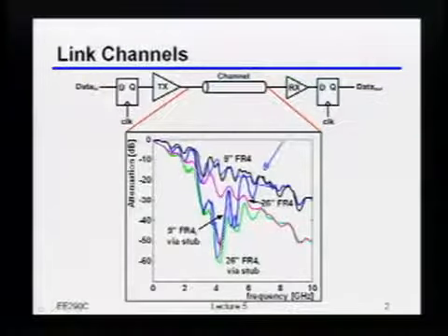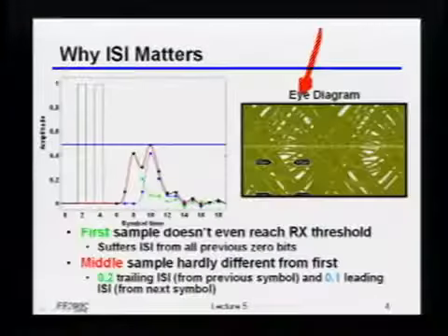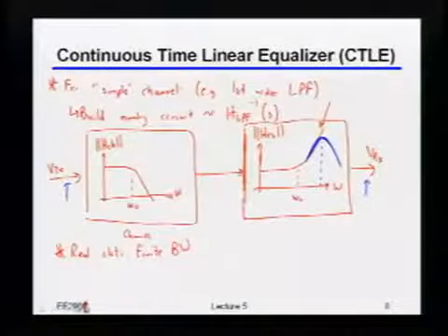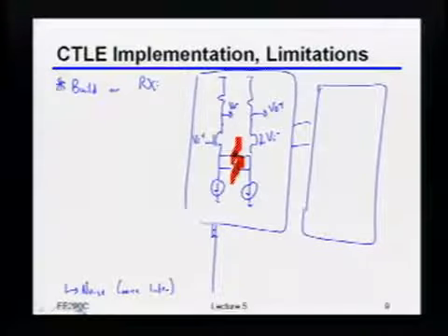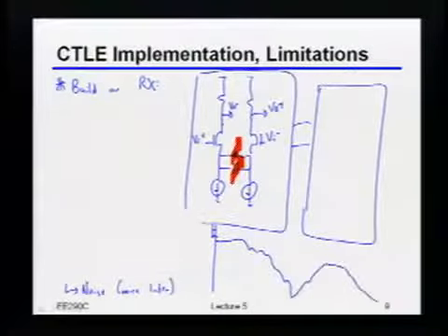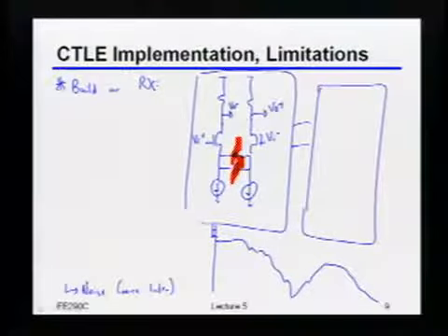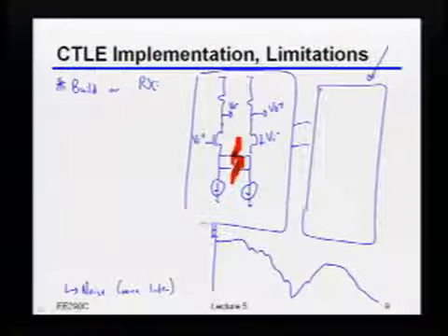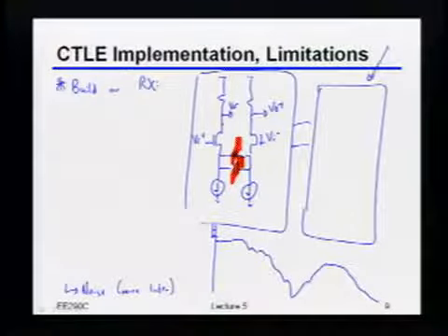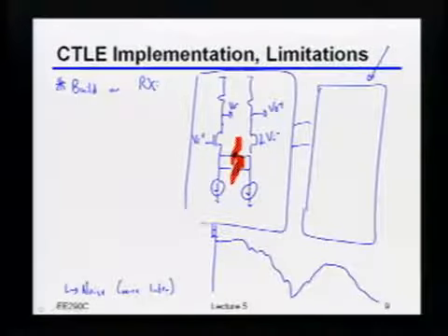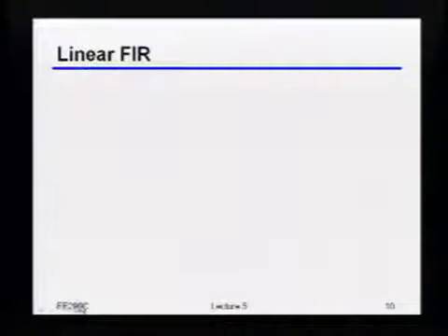Okay? So basically the meta point there is that these linear equalizers are very nice as long as you have a simple channel response. But if the channel response starts getting more complicated, again, just as an example, let's say it looks something like that, it starts getting a lot trickier to actually implement that equalizer. So indeed you could just start cascading a bunch of stages and playing with poles and zeros and doing feedbacks and all kinds of stuff like that, but at some point it just gets painful.